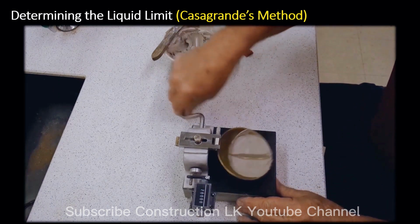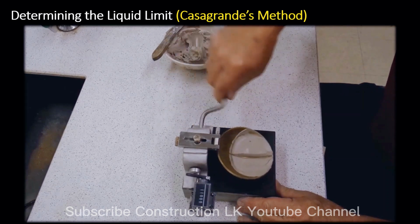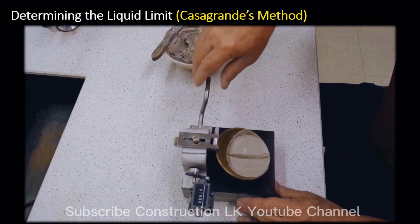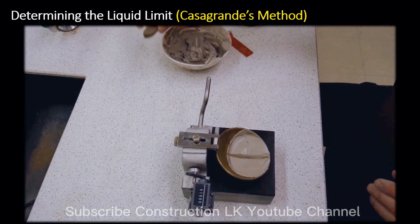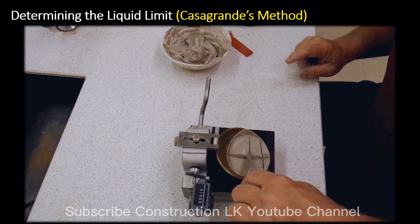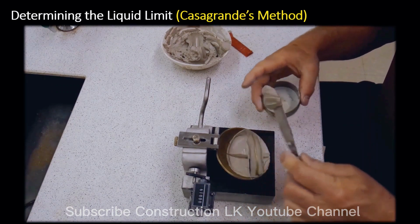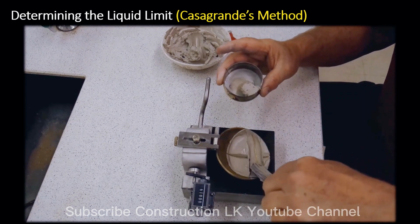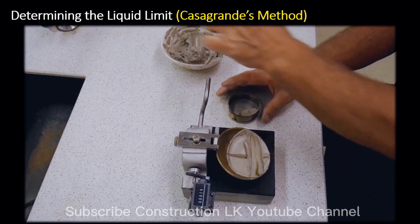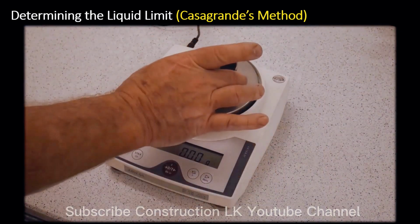Then the cup shall be lifted and dropped by turning the crank at a rate of 2 drops per second, until the two halves of the soil pat come in contact at the bottom of the groove, along a distance of 13 mm. The number of drops required to close the groove should be recorded, and a slice of the soil removed for the determination of moisture content. Sample should be taken from edge to edge of the cup to include the portion of the groove in which the soil flowed together. A spatula may be used for this purpose.